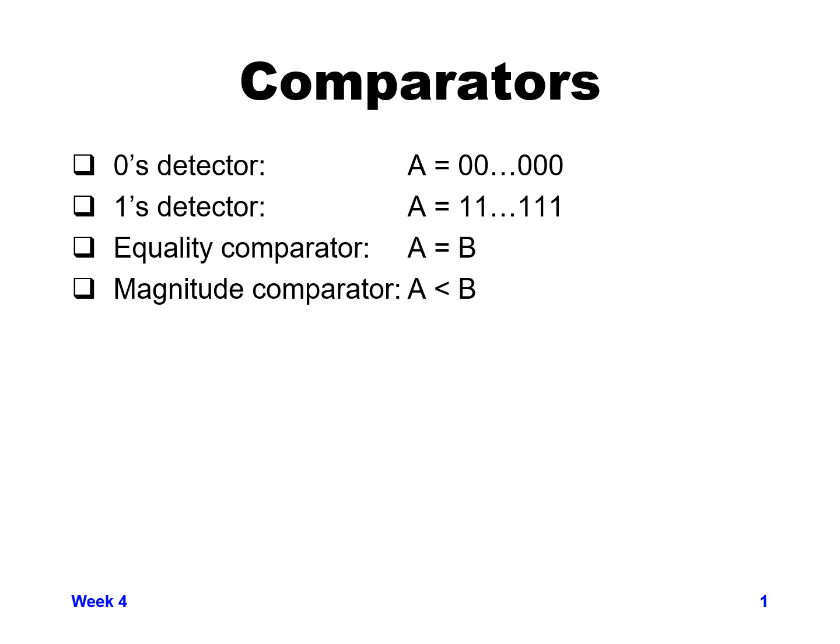The second useful one comes in depending on what computations you're trying to do. It's also useful to know, is the value that I have all ones? So that's called a ones detector. If every bit in that data value is equal to 1, then you output a single true or false value that says a 1 for all ones, or a 0 for no, there's not all ones. And same thing for the 0 detector.